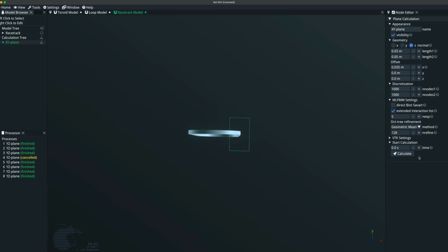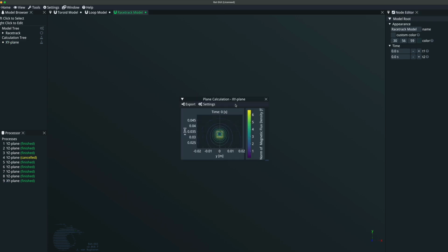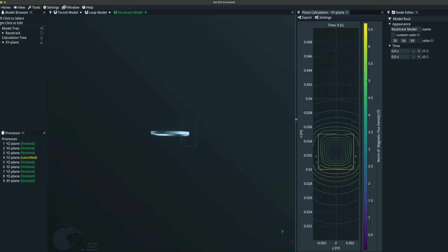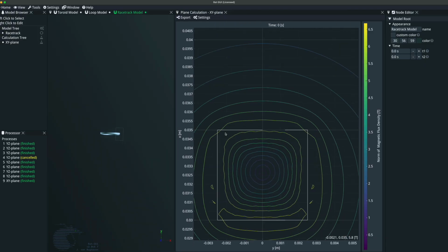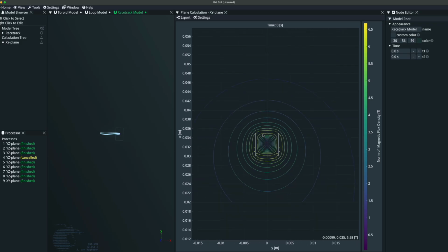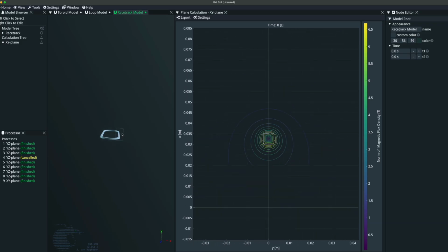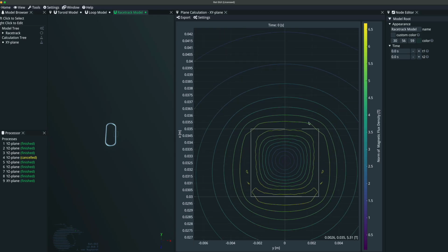I just click that here because it's easier to visualize. It is fast, right? So it's immediately done. So that's nice. But at the boundary, it's a bit wobbly. And so in most cases, that's okay. If you're not actually interested in the boundary, it's fine. If you're looking at the field of the whole plane and you want to know accurately what's inside of the coil, so the center field, right? That's no problem. But at the boundary, this is a bit inaccurate.